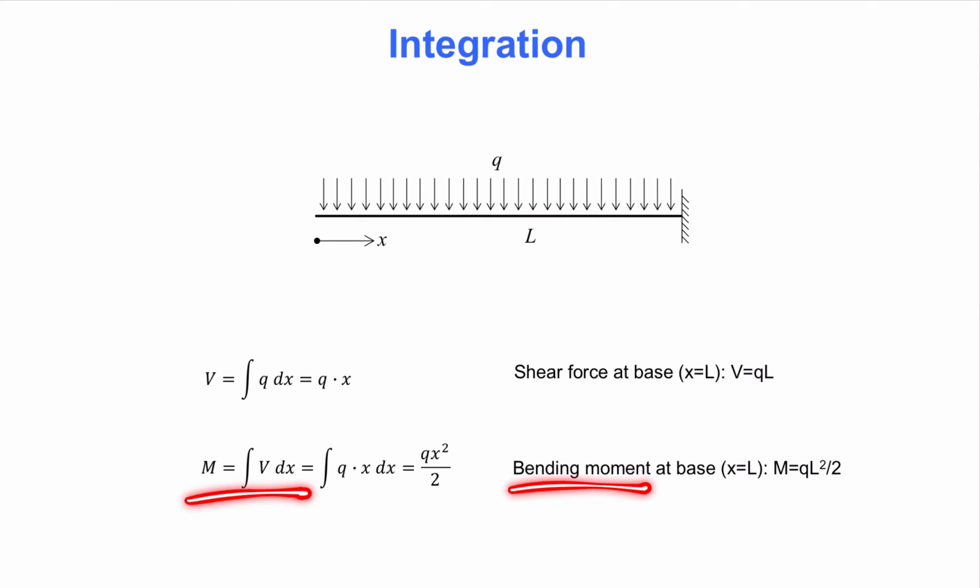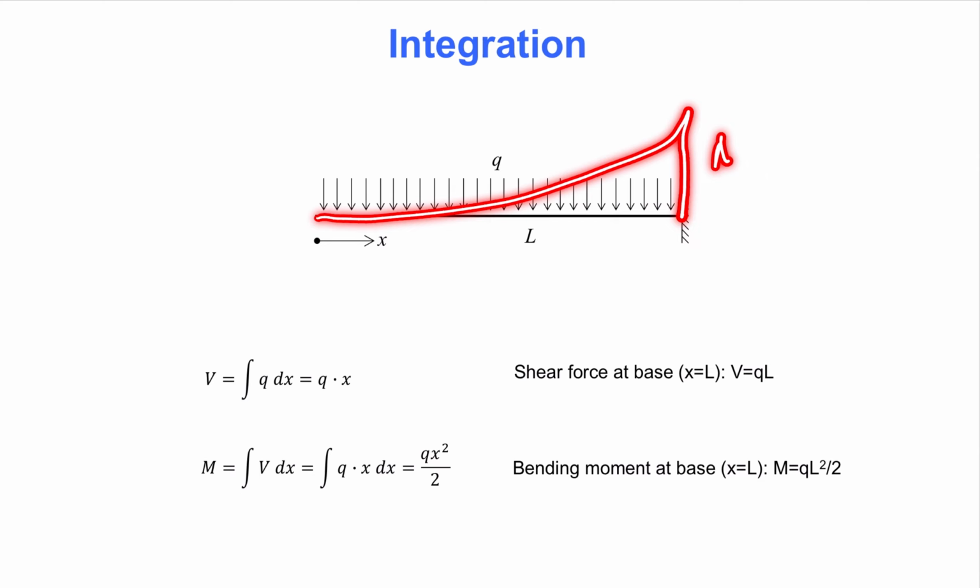This approach of obtaining the bending moment diagram as a mathematical function of the variable x is not adopted in Terje's Toolbox. Some viewers might ask whether that will cause problems in advanced methods, such as virtual work to obtain deformations, where moment diagrams need to be integrated. The answer is no, because modern textbooks have formulas for integrating all kinds of moment diagram shapes. Working with functions of x for realistic beam and frame structures would be quite cumbersome in comparison with that approach.